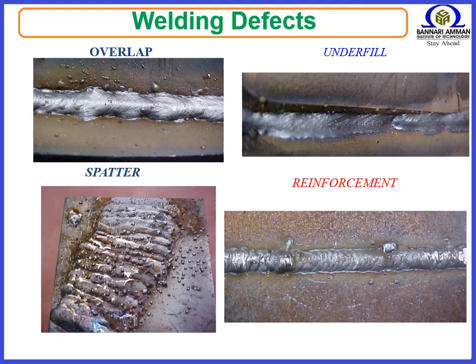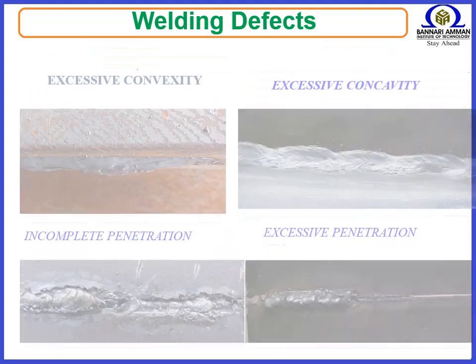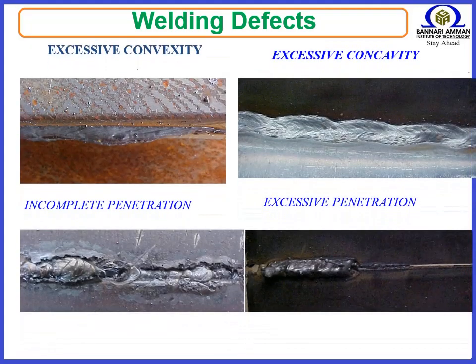Causes of spatter: the running amperage is too high, voltage setting is too low, the work angle of the electrode is too steep. Lack of fusion and incomplete penetration.